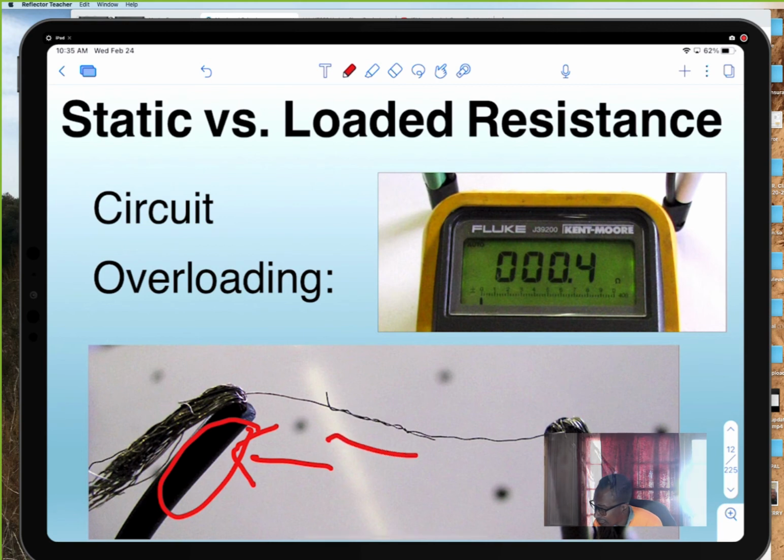I actually saw this happen on a Jeep that wouldn't start. The thick battery cable, and how you could tell is the cable was nice and red, right? But that one spot was broken internally. You could see it's like white, weak. You feel it. It just feels weak when you twist it, but you don't see it initially.